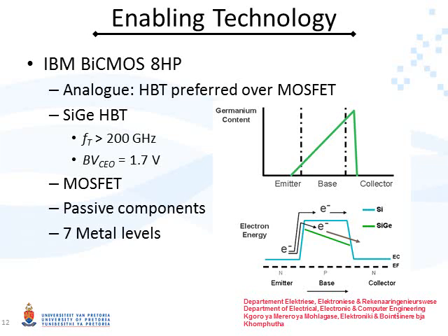At millimeter wave frequencies, system performance is affected by the device layout. The layout of the circuit will also introduce parasitics, especially in the interconnects. The PDK includes the parasitics and process tolerance for each device. The design guideline also provides a detailed analysis of each device's performance, including the parasitic values under various simulated and measured conditions for comparative purposes. The designer can therefore measure the parasitic effects for different conditions.